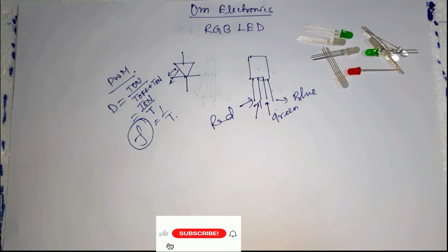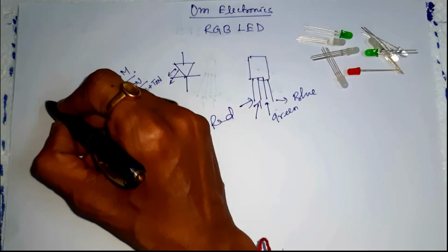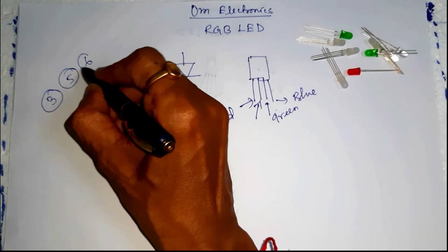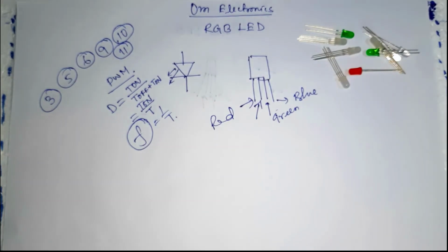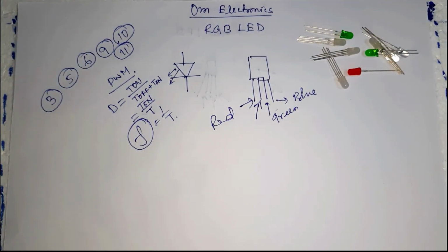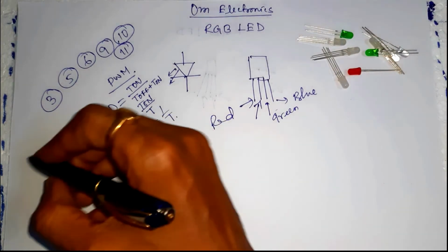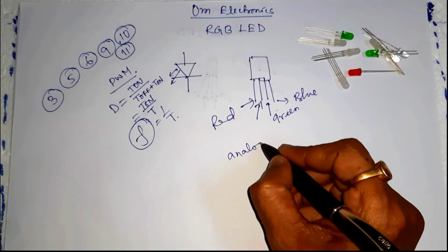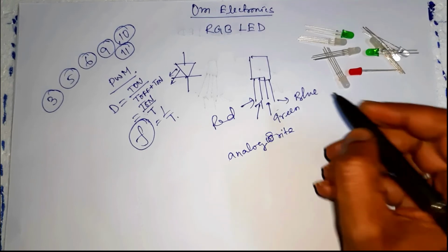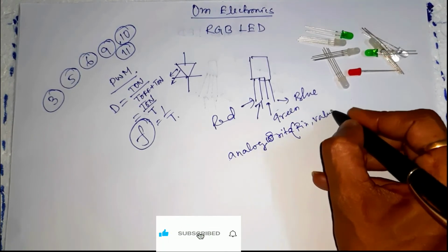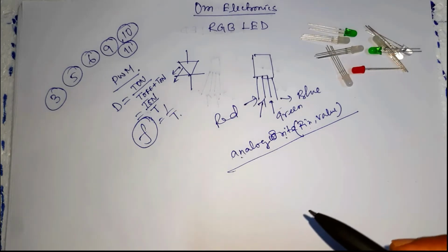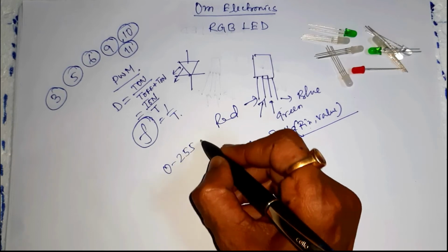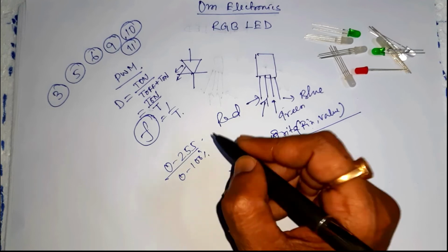Here we use Arduino to generate a PWM signal. Arduino Uno has 6 pins that can be used to generate a PWM signal, that is pin number 3, 5, 6, 9, 10 and 11. In order to generate a PWM signal of a specific duty cycle, you need to use the analogWrite function. Here the value varies from 0 to 255 for 0 to 100% duty cycle.